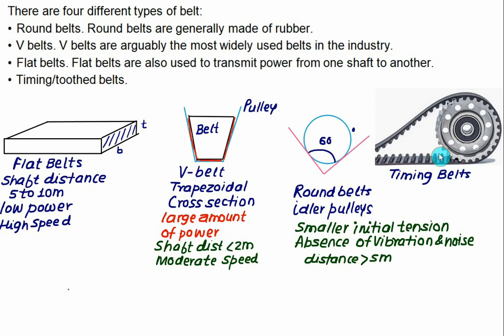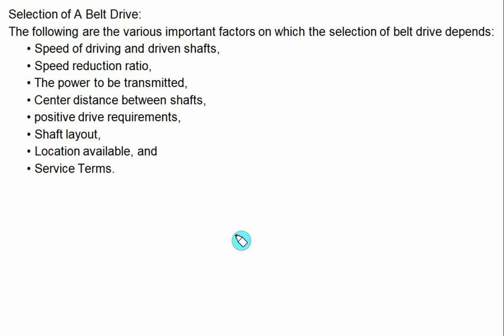Toothed belts do not slip at all and are used in applications where maintaining accurate timing and position is critical. As a result, these belts are also known as timing belts or synchronous belts. They are commonly used in automobile and motorcycle engines to power and time camshafts. Timing belts are a positive transfer belt and can track the relative movement. These belts have teeth, so where precise and reliable transfer is required, we have to use the timing or toothed belts.